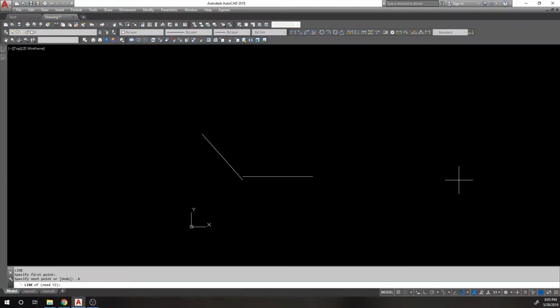It's locked. No matter where I'm at, I have locked it to an x coordinate, which is the end of this line. I can't go any further or closer than this coordinate. Okay? If I turn my ortho on, it just stays to that point.